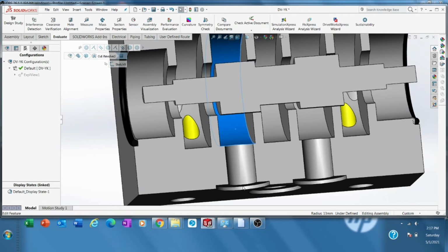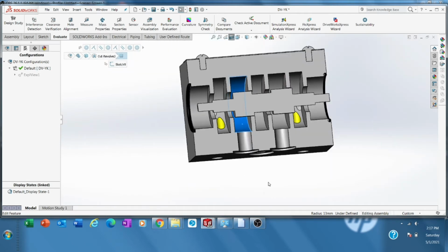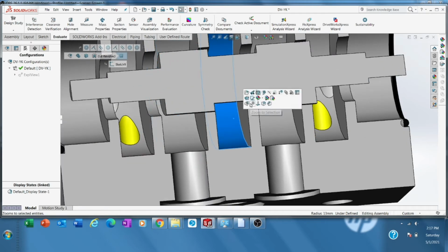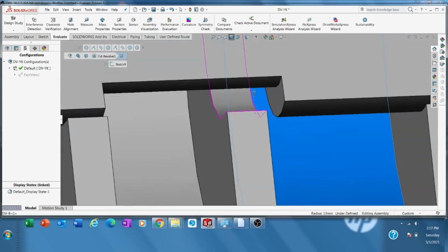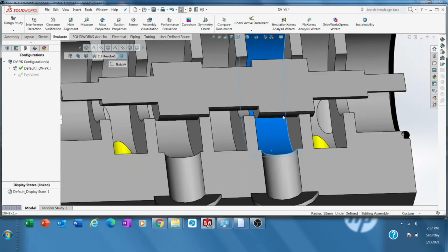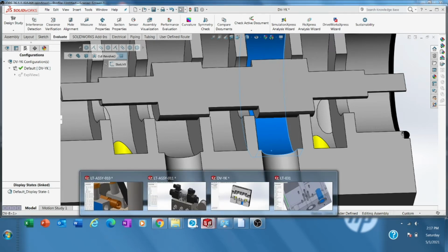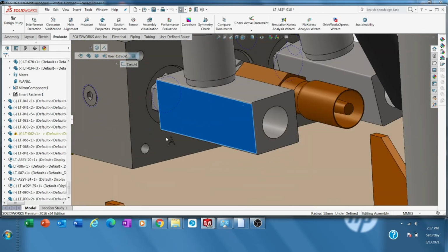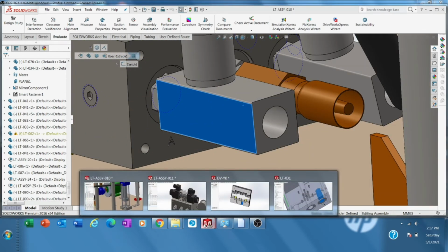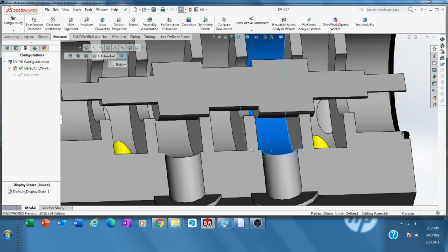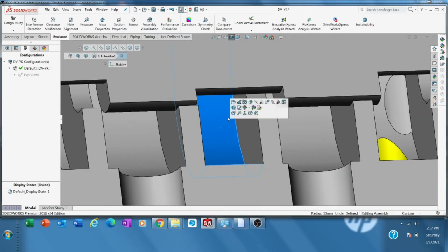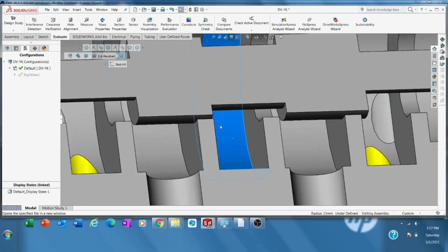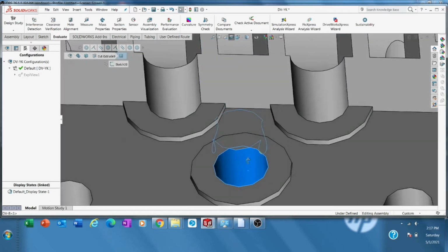It's only possible to this direction, and then this direction will flow to the hydraulic cylinder. But here, see, there is an opening. It means the oil from this port that goes to this A port now has a chance to move to this zone, and this zone is the tank port.